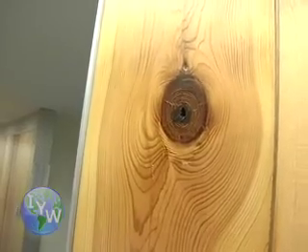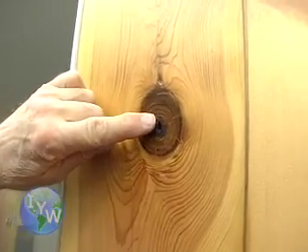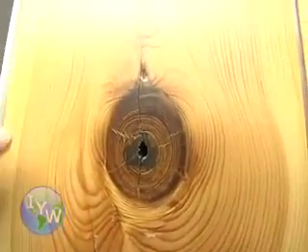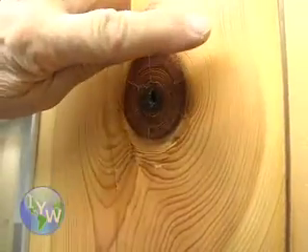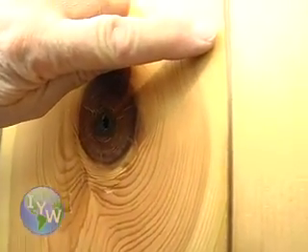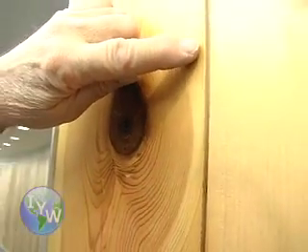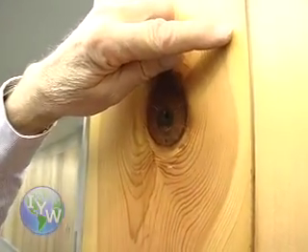As we look at this piece of wood, we see that there is a knot in it, and we see that the growth rings that surrounded the knot are all moving out in various directions. When the growth rings hit the surface of the piece of wood, they are at an angle to the surface. That is going to have a dramatic impact on the strength of the wood.